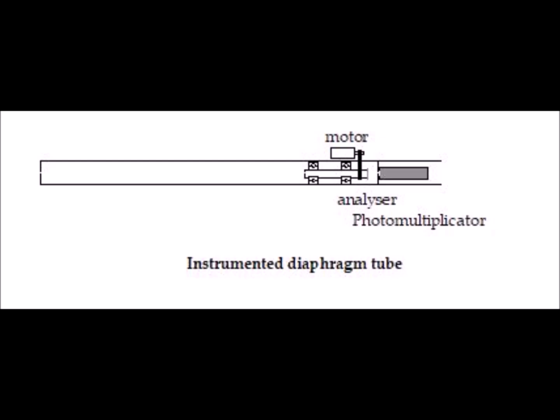The main tube is coated on the inside with a layer of anti-reflective paint, and has in its middle part a series of about 10 wads of black polyurethane foam, each 1 cm long, pierced with a tubular orifice 2 mm in diameter in the axis of the main tube.